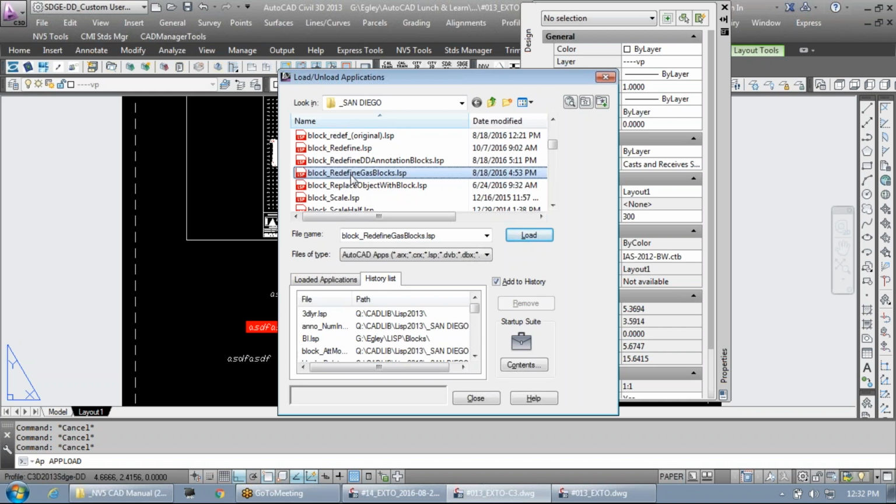I came up with 2 LISP routines to add some polar angles and incremental angles. So if you're into polar tracking, please see me on those. They're pretty neat to add some angles. Those are useful if you're laying out electrical lines or gas lines or water lines and you need to deflect your pipe at certain angles. Those LISP routines help you walk through that process.